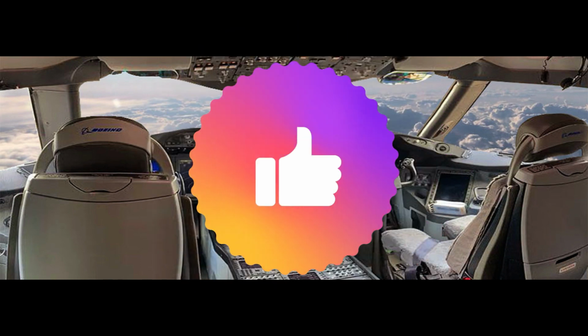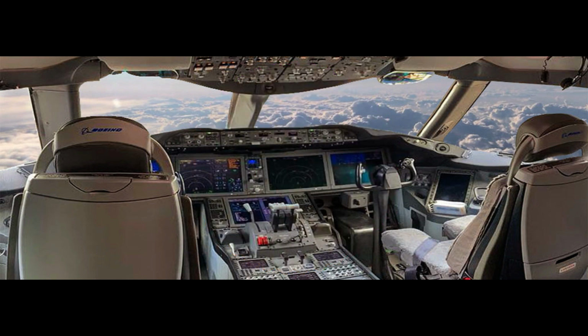2. Turbulence. The Pilot's Operating Handbook, (POH), and FD/Autopilot Flight Manual supplements for many aircraft discourage or prohibit use of the autopilot's altitude hold function during moderate or severe turbulence. Some FD/Autopilot systems may default or disengage if certain trim or control limits are encountered during turbulent conditions. You should consult the flight manual to ensure the aircraft is not operated outside specified limits. The aircraft's flight path and mode indications should always be monitored to ensure what modes are active.